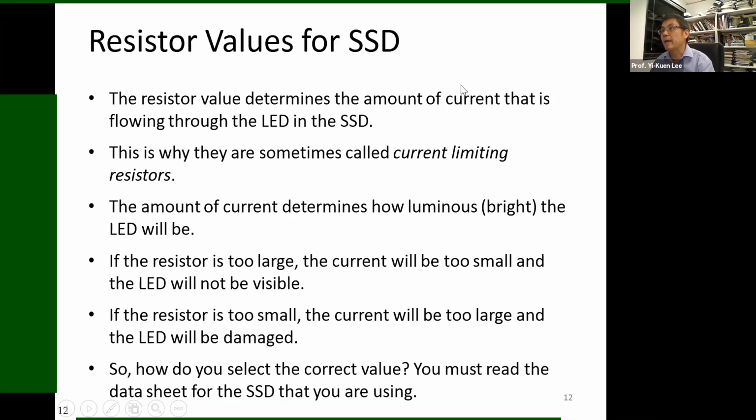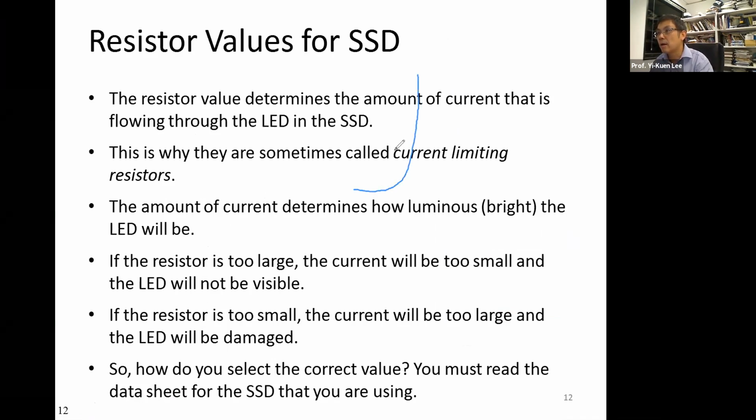And then of course, again, how we pick the right resistor for the LED in this display. As I told you, LED is nonlinear behavior, so you have to have an additional resistor. Its behavior is nonlinear. We have a VD and ID, right? Nonlinear, so if you don't add an additional resistor in series with this LED, then you will burn your LED. Okay, so this is common.